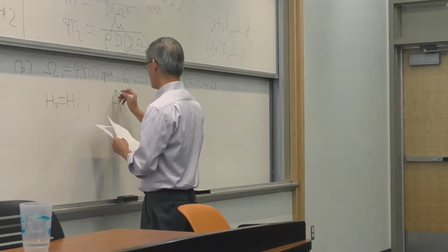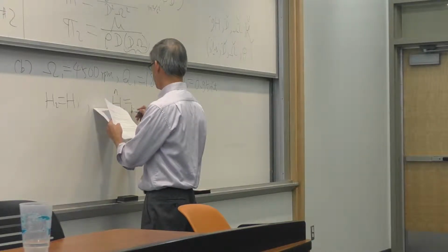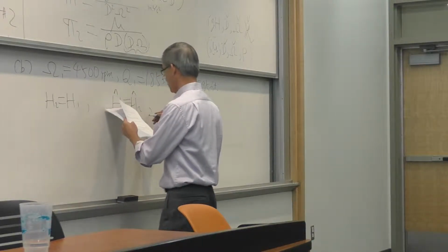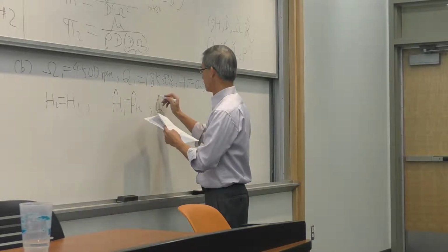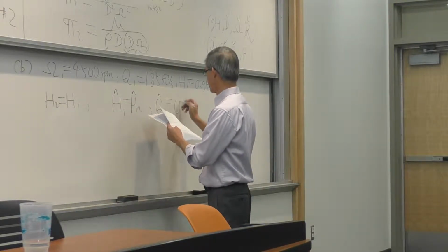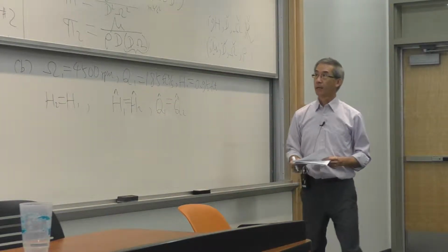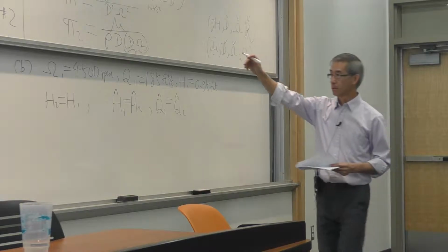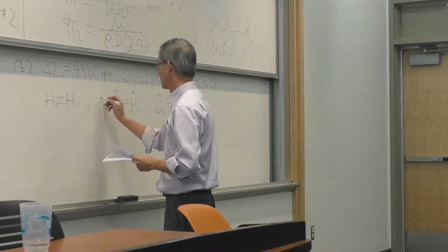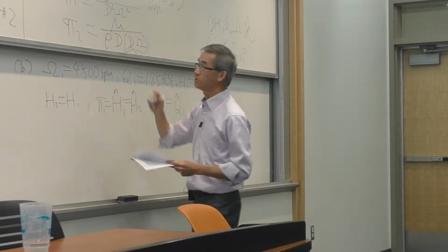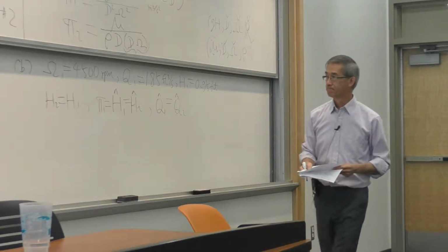But due to similitude, my pi term, that's the head, is the pi 1 that you get here, must match between my model and my prototype.